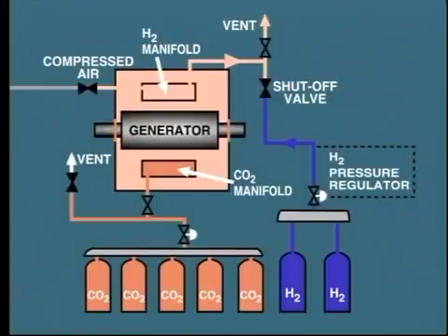During this process, the gas inside the generator casing is monitored, and when this indicates close to 100% CO2, air is admitted via the upper manifold to clear out the CO2. Now remember, carbon dioxide presents a suffocation hazard when encountered in a confined space. The total time required for purging may take several hours.